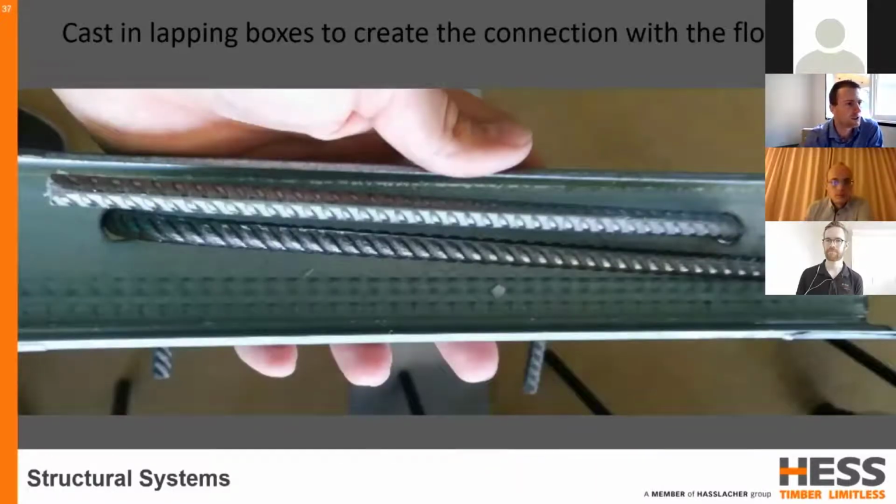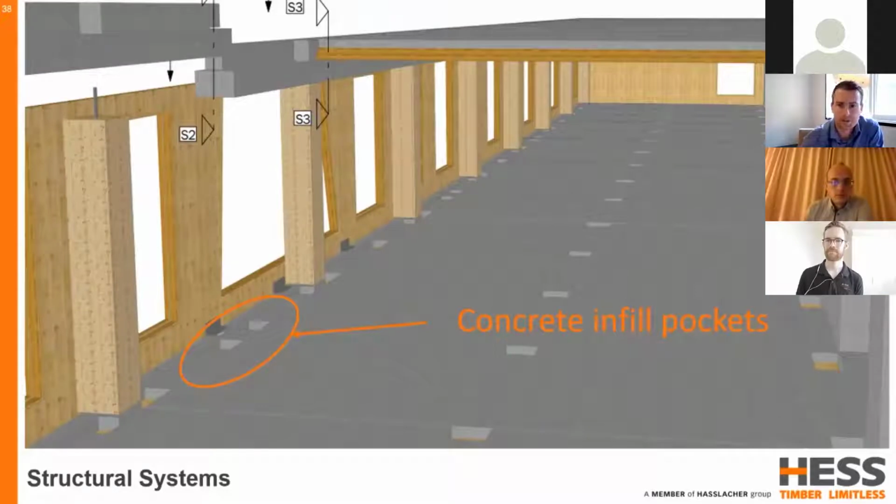So they're essentially a cogged reinforcement bar which is cast into the edge beams and then bent on site. So the bars were bent into the matching pockets that were cast in the floor slabs before, which obviously also lapped with reinforcement that was precast within the slabs themselves, and then it was infilled on site afterwards.